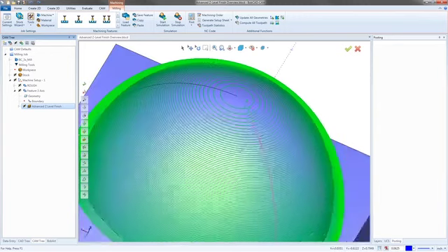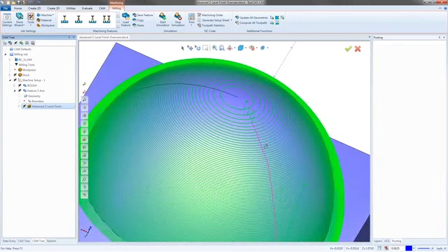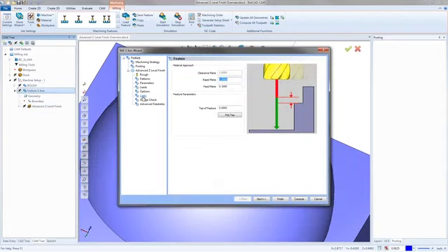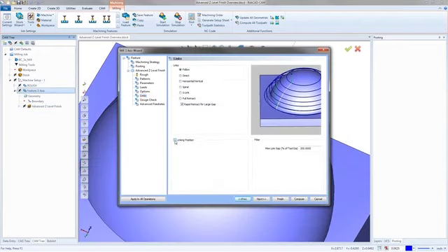Now you can also see where we're linking, so how we're connecting one path to another. One of the new things that we added the ability to do is on the links tab, you can set your linking position. So I'm going to start by not shifting anything. I want to leave that at 0. Or actually, I'll start with the shift.